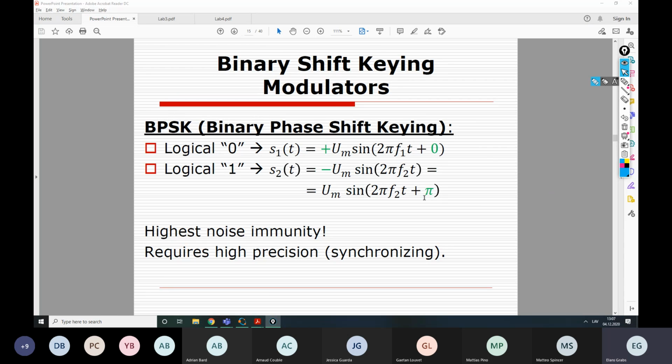But anyway, we use phase shift keying only in the case when we have very low signals, such as in space applications, such as the slowest Wi-Fi operation mode. It also includes binary phase shift keying for the case when you are quite far away from your router, because which modulation is used for Wi-Fi actually depends on the position of your router and your device.